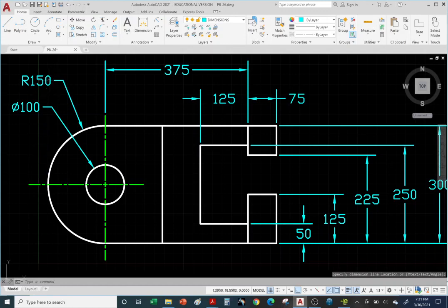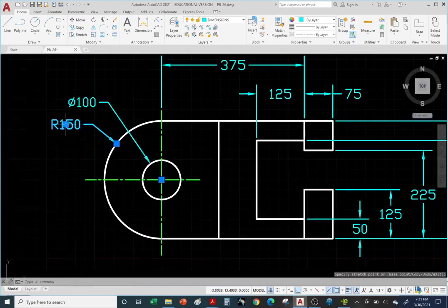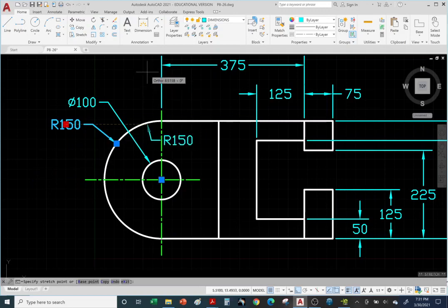It doesn't matter which one is at the bottom. We can move the radius downward if we want, or leave it up there. One thing you don't want is a flat leader. You don't want a flat or vertical leader. Try and avoid it. You want to give it some angle, a 45, a 60, a 30-degree angle. So either one is acceptable.